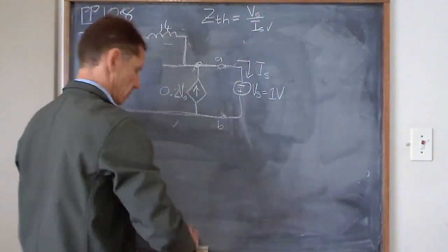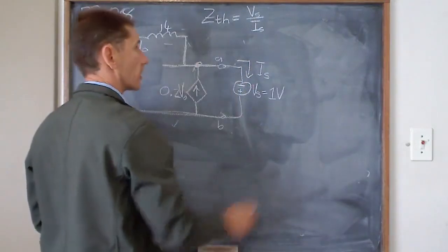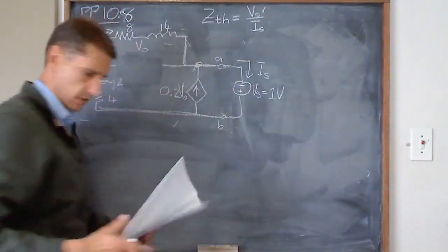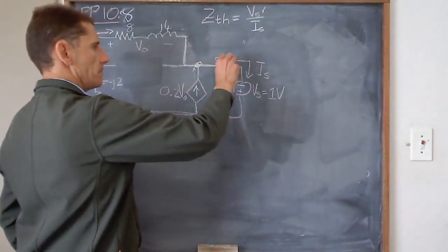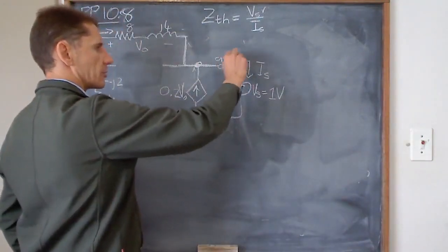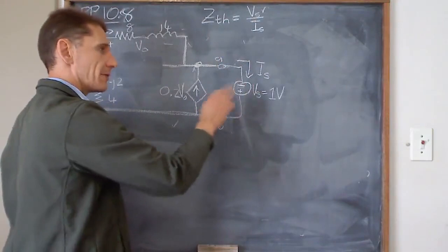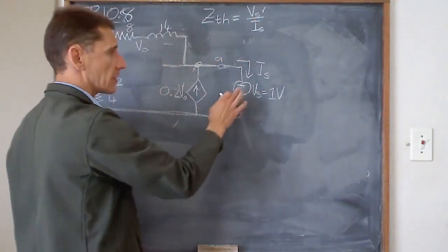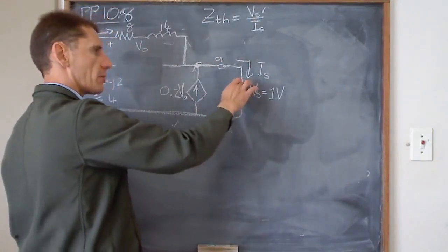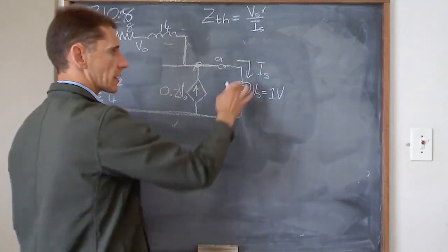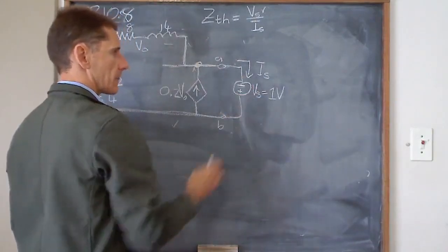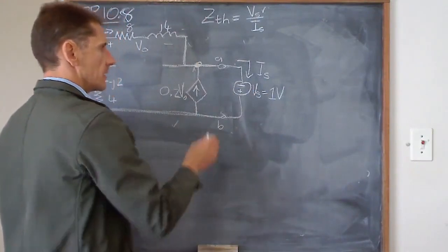So now we've got this. Okay, now I don't have those calculations, so let me just put this down. Now I need to calculate what the current is. Note that this is now a source, so don't get confused with the current going from positive to negative. In an independent source, the current goes from the negative to the positive side.